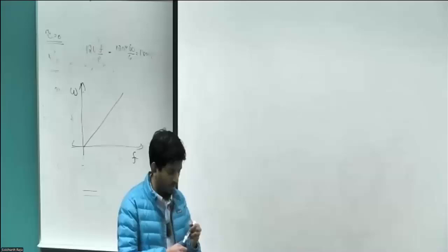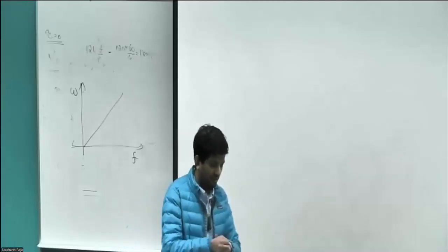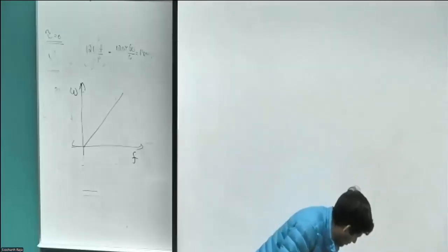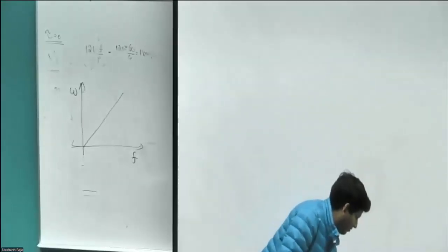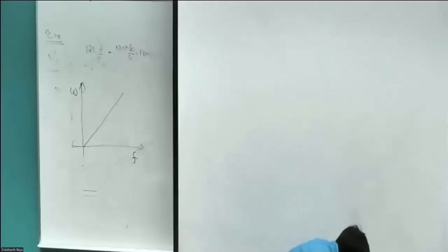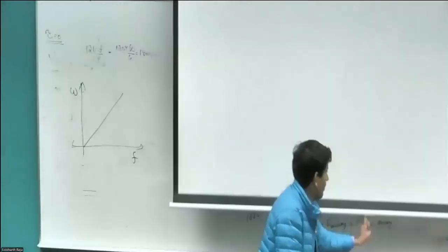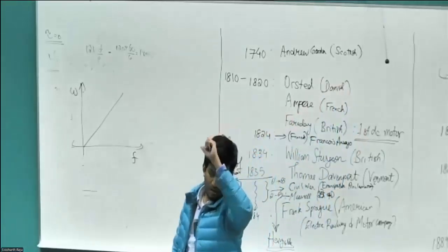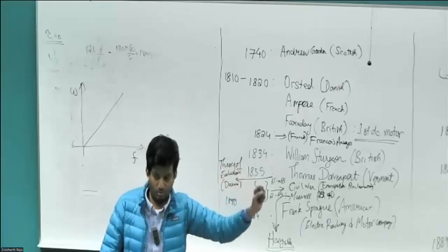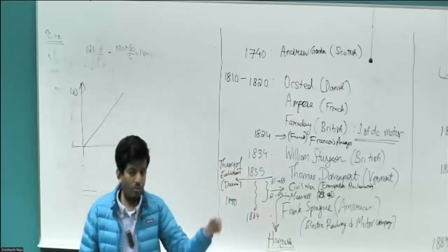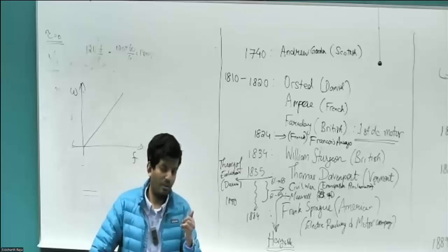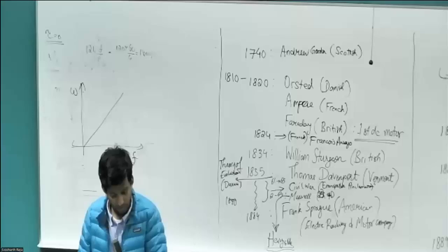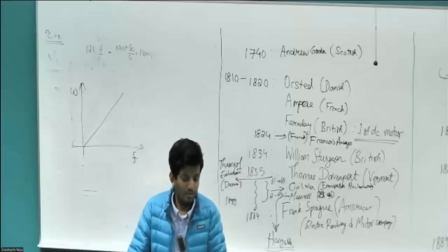So this is a very big problem when it comes to permanent magnet synchronous motor, because if we were to directly connect this motor to the grid, let's assume that's somehow feasible, as we'll see in a minute, that is not, and for whatever reason, we apply a load torque that's large enough that the rotor comes to a stop, there is no way to bring that motor back up online again. Right? As we saw, you can reduce the torque all the way down to 0 and the motor is not going to start rotating again. So this is the first problem.